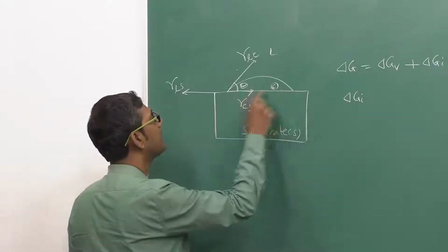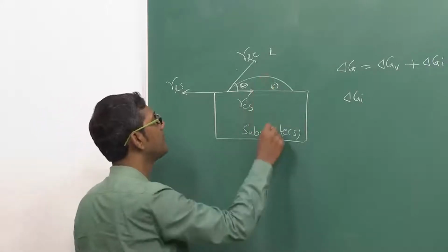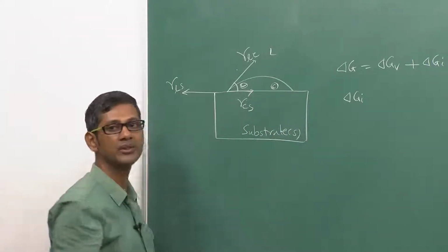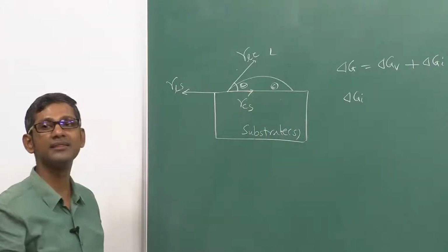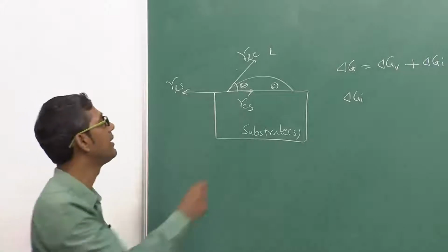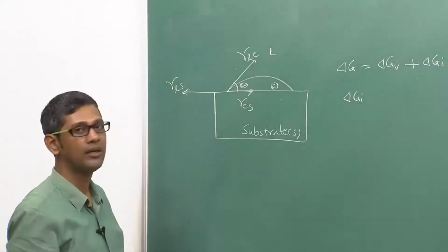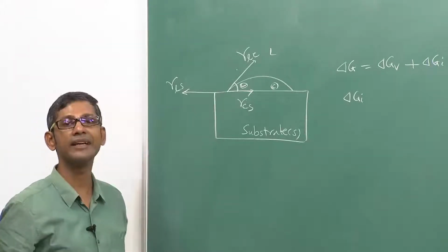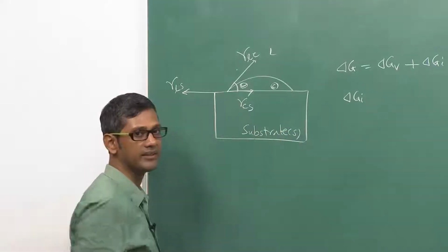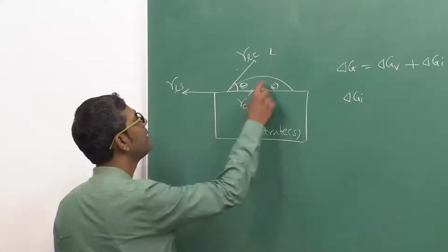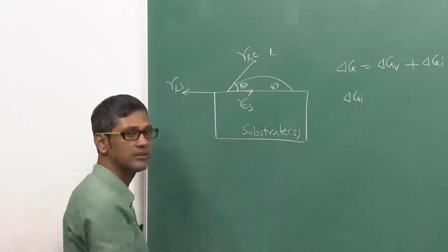So this energy is recovered; the surface energy because of the substrate and liquid which was there earlier is basically taken back by the system. On the other hand, two new surfaces are created. What are these? One is between the liquid and the crystal, the other is between the crystal and the substrate, right.